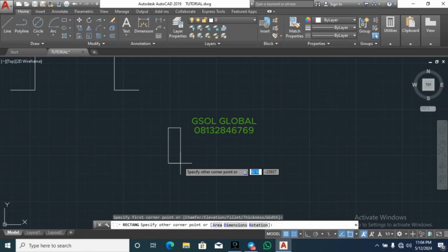What dimension am I going to use right now? Remember, the first one is the length, the second one is the breadth. So take note very well. I'm going to insert the length: 10,000, let's use, okay, I'm going to use 10,000. I'm already used to it. Let's use 8,000. After selecting, you see that you're having a problem going to the next box, which is the breadth. To go to the next box, you will have to use your tab key.